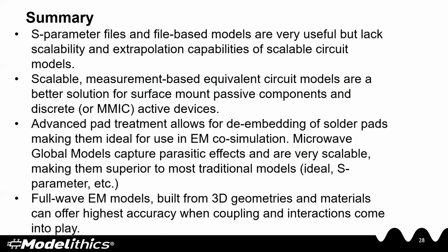So in summary, S-parameter files are useful, but they lack the scalability that the scalable circuit models offer. Scalable circuit models are a better solution for designs that give the designer flexibility and much more features that are not available with S-parameter data files. These scalable models also allow you to de-embed the solder pads so that they can be used in EM circuit co-simulations. And then the full-wave 3D EM models are very useful for scenarios in which coupling and interactions can come into play.